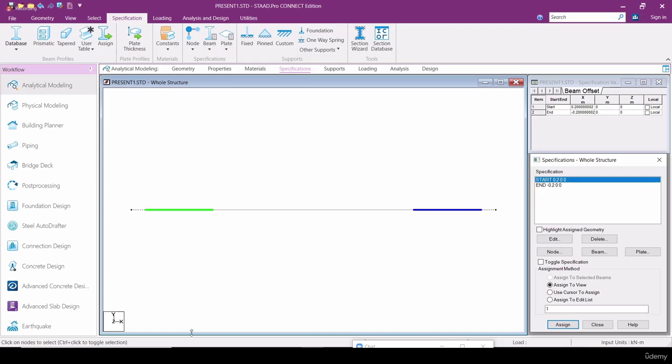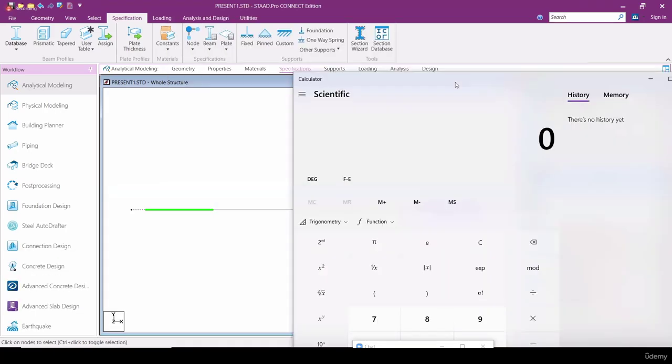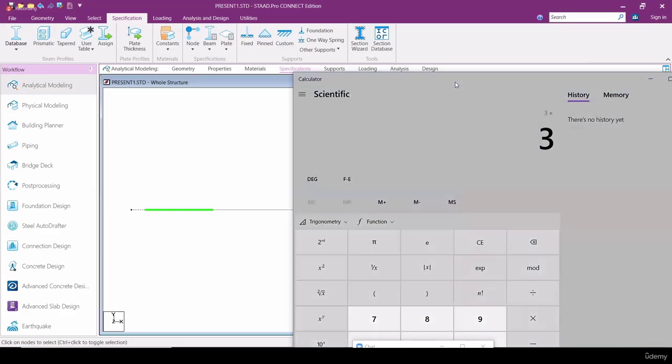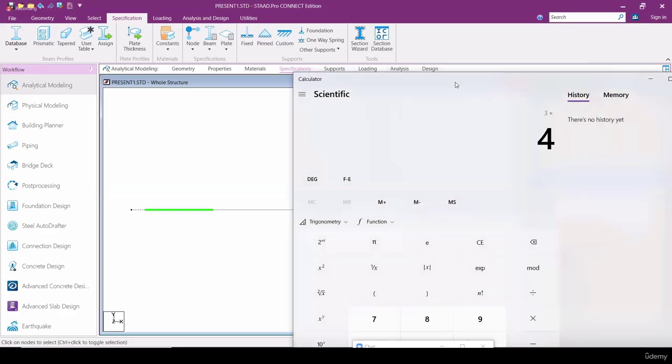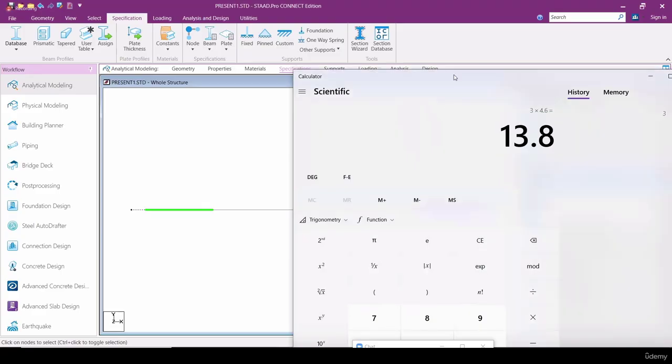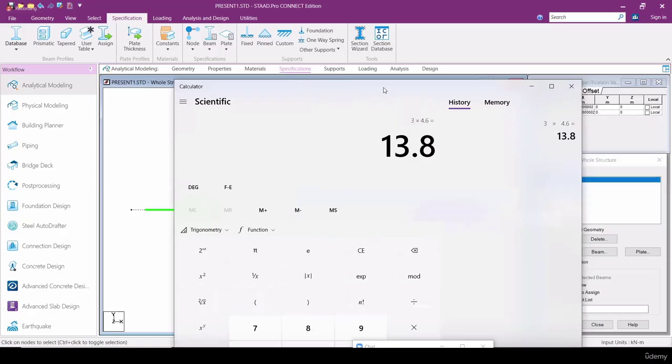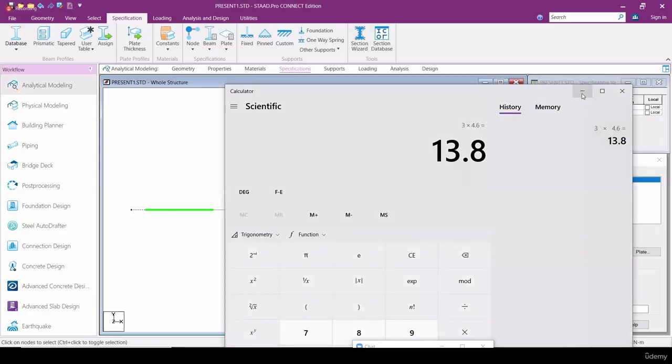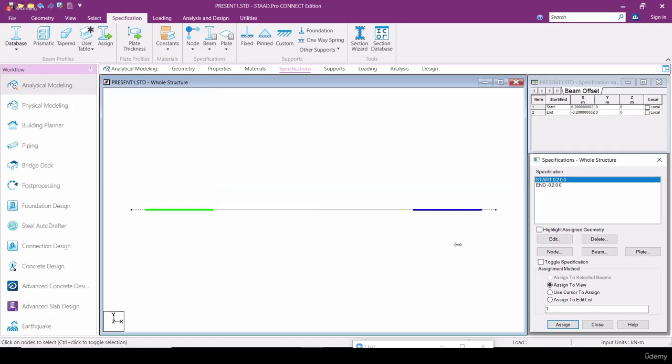I'm going to calculate in front of you. So the 3 kilonewton per meter load times the effective length, which is 4.6 here. So instead of 15, it will take 13.8 kilonewton force only. So the shear force also gets reduced, the bending moment also gets reduced, and thus the section will become somewhat economical. That is what someone asked about, right? Have you understood clearly? Yes, sir.